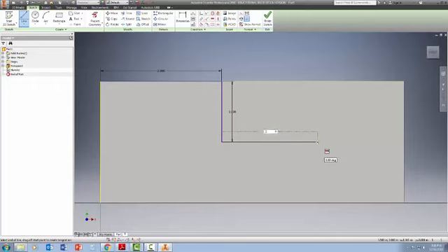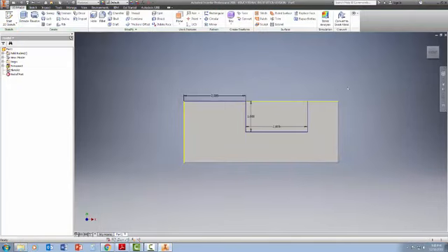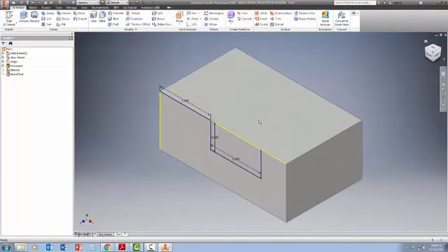So I'm doing 2, enter, and then because it's still attached, I want to make sure it comes up 90, and bring this up. I'm just scrolling up, and it says 90 degrees on the left hand side. You see it? Now it says 86. I bring it all the way up. I don't even have to type in anything. All I got to do is just bring it up to that line. It automatically makes it 1 inch. I'm at 90 degrees, and I click. That's it. Right now I want to do finish sketch. So now I have a sketch that's finished.